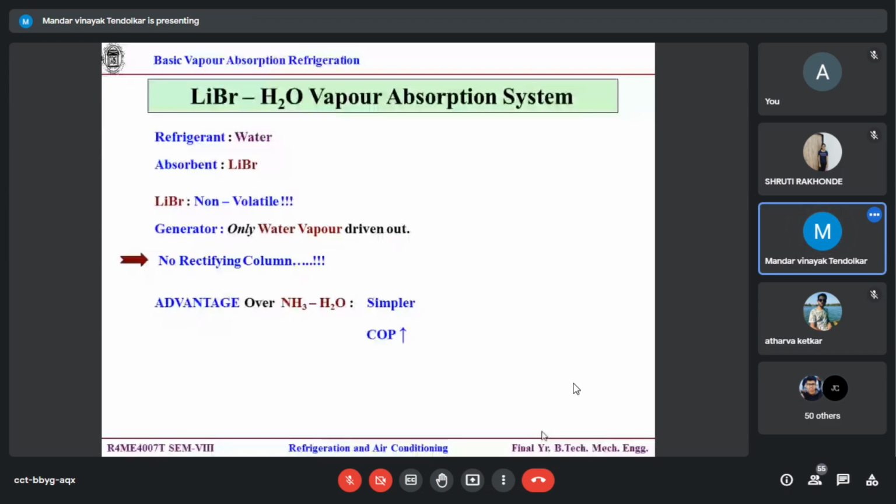LiBr. The only limitation is that since you are using the refrigerant as water, you cannot go to ice. How will it flow in the evaporator? So there is only limitation as the temperature limits. You cannot go below 4 degrees Celsius. Anomalous behavior of water. So if your refrigeration requirement is, let's say, 8 degrees Celsius, 10 degrees Celsius, then you can use it. You cannot use it certainly for -5, no? It will become ice. Okay? Fine. So that is the only limitation.